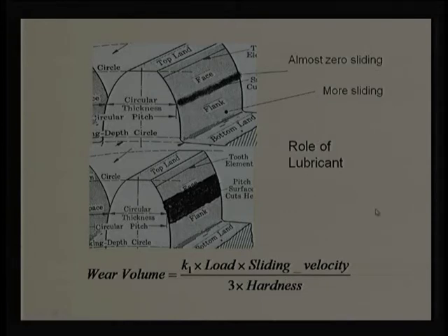So, it is heavily dependent, and if we choose a bad material having lesser stiffness, naturally the wear will be more. If we apply more load, wear will be more. If we apply more sliding, wear will be more.